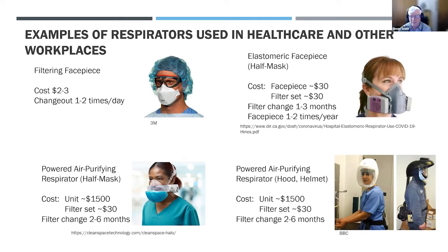These are rather more expensive, but they do offer more comfort and a higher level of protection, generally because air is being blown in by a fan of some kind, and then the expulsion of air around the periphery ensures protection. So these are examples, but the general guidance one would have if one is exposed to generally low levels of contamination is that the filtering face piece or elastomeric types would probably be adequate.